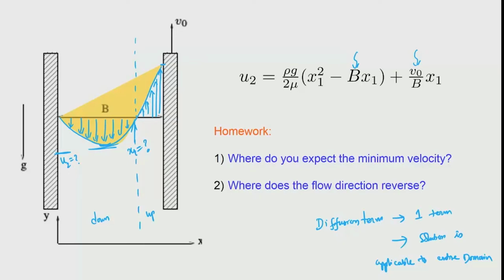And we are also going to look at the reason why this is called the diffusion profile of the velocity field. The reason is that what is being diffused is the momentum. Okay. So, the momentum that is being dispersed within the medium because of the wall conditions is the reason why the viscosity is playing a role. So, these are all basically solutions for viscous liquids only, which luckily for us in the metallurgical domain is applicable, because liquid metals and slags are generally very viscous.